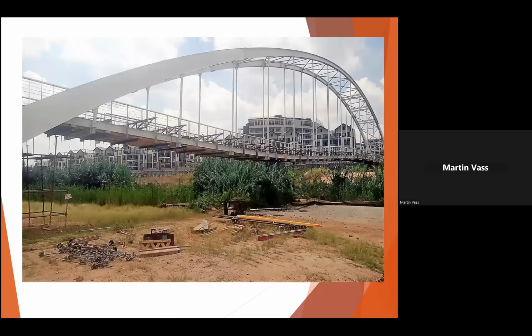You can see it's badly deformed. We still believe the arch is competent. There's nothing wrong with the arch itself. It's just this deck has to be removed and replaced. In the new design we're taking the concrete weight away, and we're putting a lightweight timber decking across this bridge. So that is the redesign. At the moment, the bridge looks like that. No remedial work has been done.